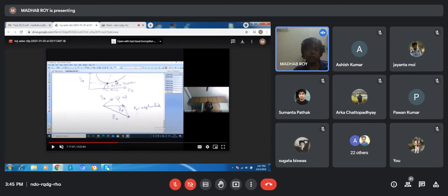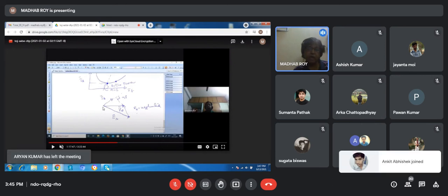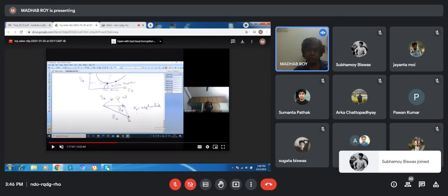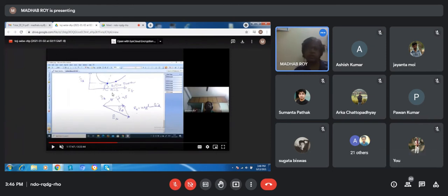What will be the phasor diagram for this point? You will see that the induced EMF will be EA, and that will be coming down because here the armature current IA will lead the terminal voltage. Now if we extend, this drop is called the jXs IA, which will touch the current line at 90 degrees. This is the phasor diagram concept. Those who know the phasor diagram drawing for the synchronous motor can understand this. Got my point? Yes, sir. So this is the point of over excitation.